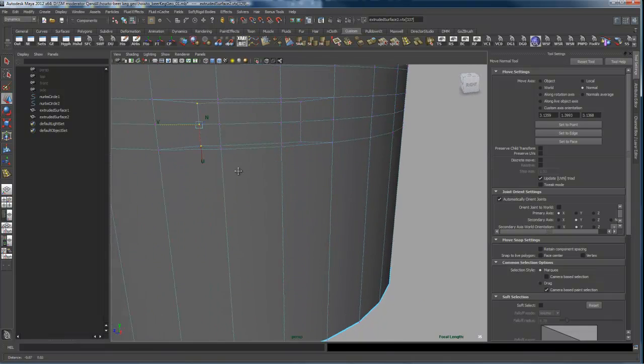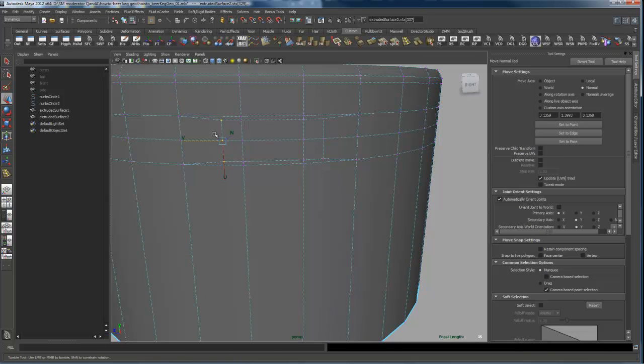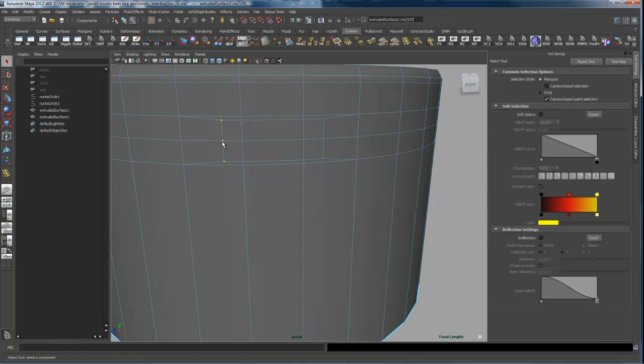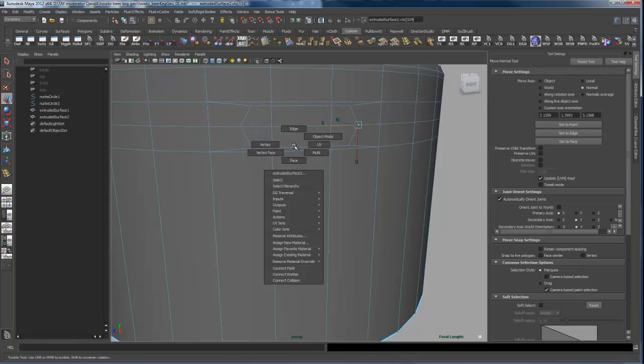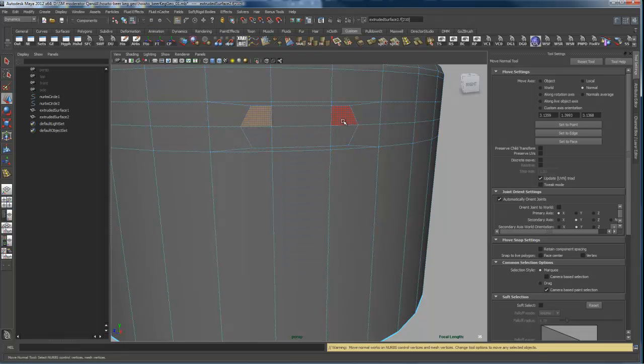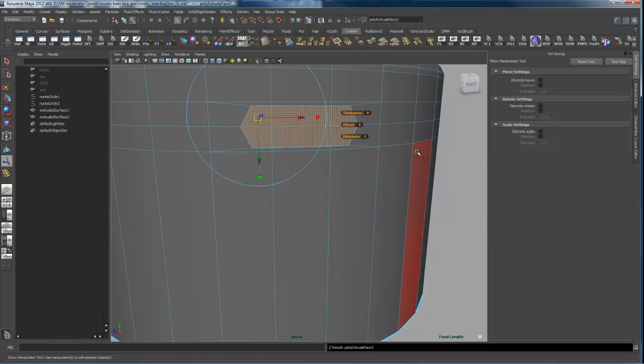And then what I can do, and I'm just eyeballing this, now I can take this middle one, because I ultimately want to get that rounded shape, right, when I smooth this. So what I can do is pick this middle vert and just pull it out a little bit this side, take this middle vert, pull it out a little bit that side, and then what I can do is take these faces and then once again give myself a little boundary. I'm going to extrude those again.